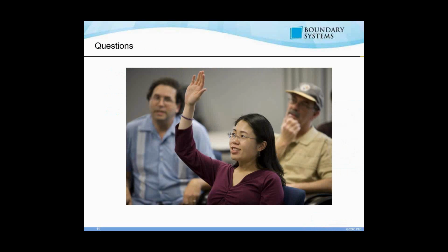So say, for example, the customer asks for a design change and we make a change to this model, we could still go back to that behavioral modeling feature, and we could rerun the analysis on there. And then it'll rerun it based on the current new model. It'll adjust the dimensions if it needs to, and it'll get you another result that's feasible, if that's within the design space of the model.